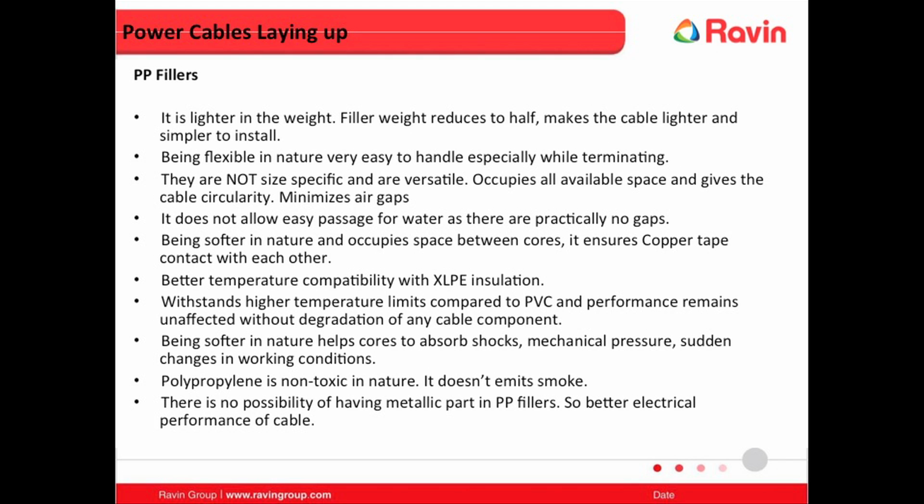There are various advantages of PP fillers, like it is lighter in weight, flexible in nature, occupies space between the cores and does not allow passage for water, and has a better temperature compatibility with XLPE insulation. It enhances the electrical performance of the cable.